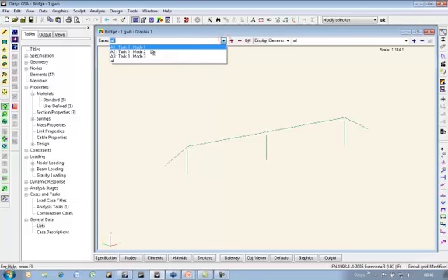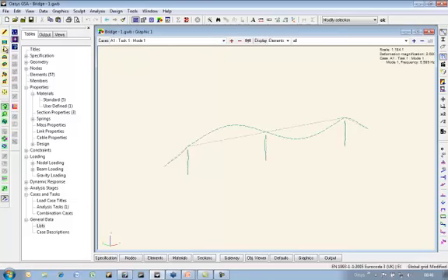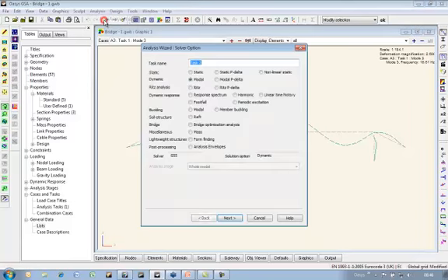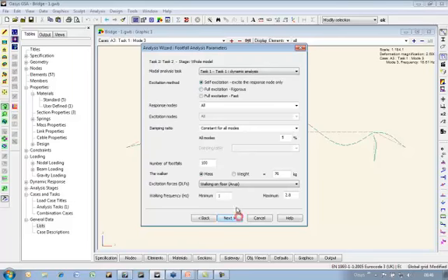And what we then get is a first frequency of 5.7, and a further frequency of 18, so that's strictly speaking outside our 15 Hertz range. This is quite a chunky concrete bridge, so if we do the rigorous analysis, damping is again going to be low.